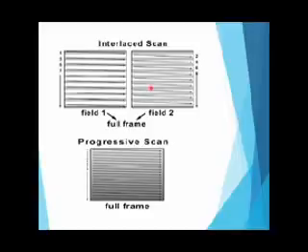In HDTV, both the video and the audio signals must be digitized by A to D converters and transmitted serially to the receiver. Because of the very high frequency of video signals, special techniques must be used to transmit the video signals over the standard 6 MHz bandwidth TV channel. Multiplexing techniques must be used because both video and audio must be transmitted over the same channel.